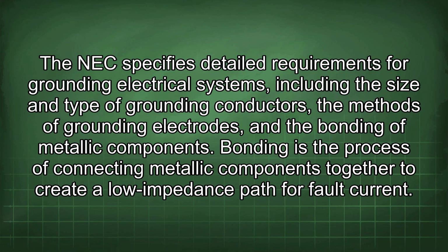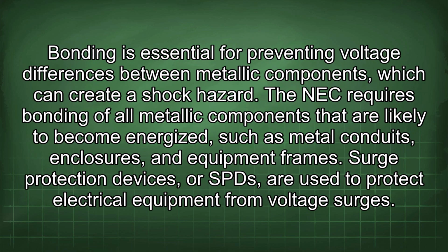Bonding is the process of connecting metallic components together to create a low impedance path for fault current. Bonding is essential for preventing voltage differences between metallic components, which can create a shock hazard. The NEC requires bonding of all metallic components that are likely to become energized, such as metal conduits, enclosures, and equipment frames.